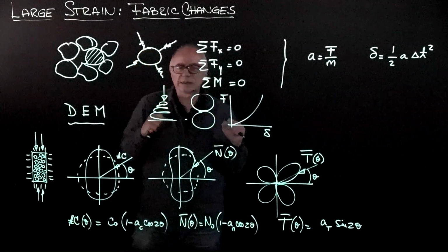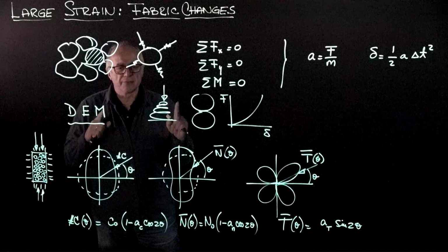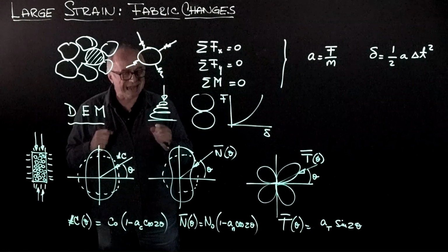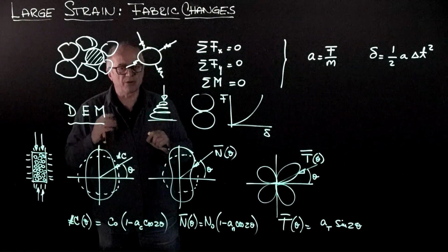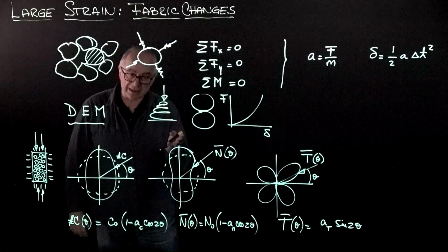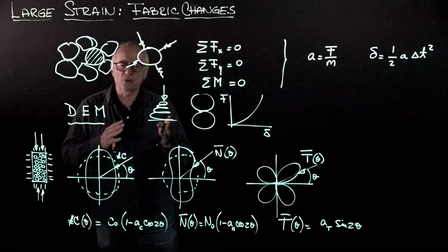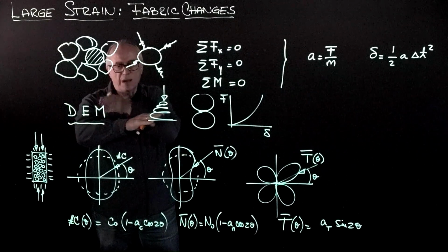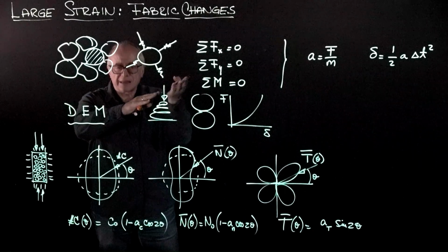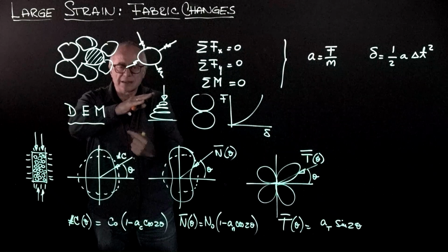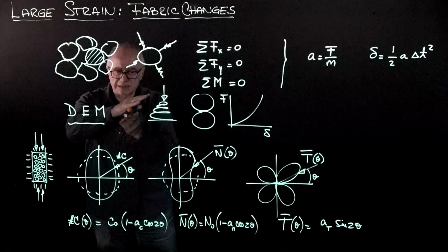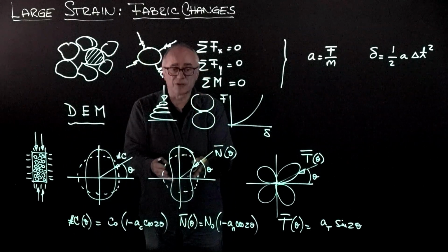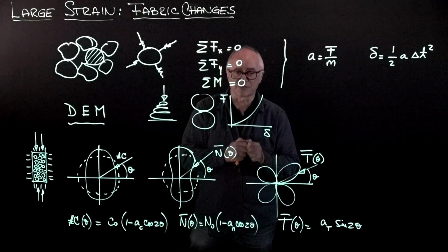Now, if you go back to an earlier presentation on Mohr circle, before we drew the Mohr circle, we actually plotted the polar diagrams in the polar coordinates. We plotted the shear stress and the normal stress that would be required to preserve equilibrium of an element subjected to sigma 1 and sigma 3 if I chop off the element and I put equilibrating stresses on that plane, and they were looking pretty much like this diagram of normal forces and this diagram of shear forces.